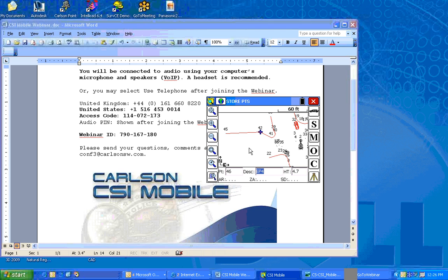So let's say I don't even know ahead of time what the fence line code is. I'll just be lazy and stay with EP4, which it defaults to. Notice this line was EP3. It's intelligent to say you're going to do another EP, so it's probably EP4. I'm going to change its mind here in a second. I'll take the shot at 300. I hope this will work.